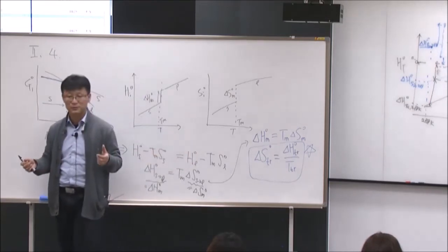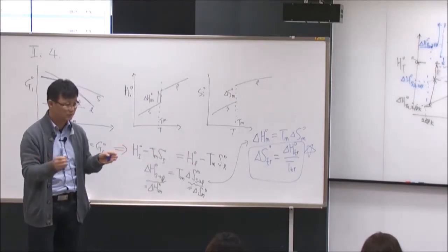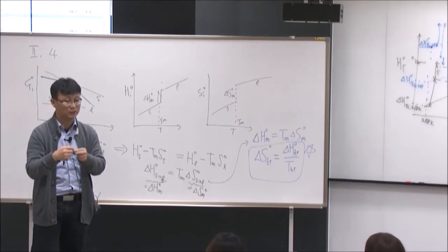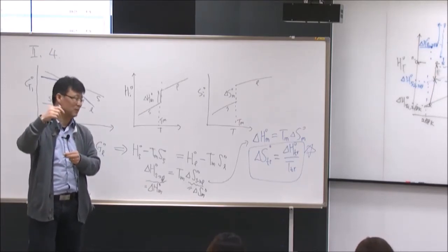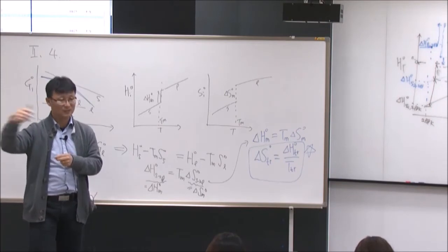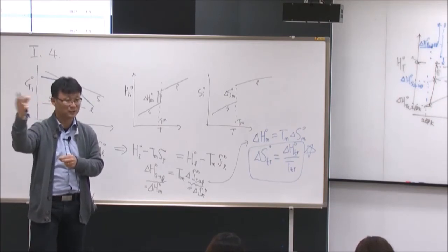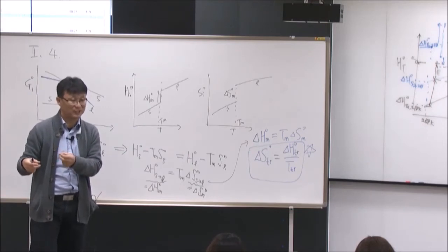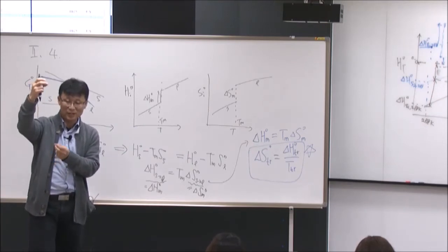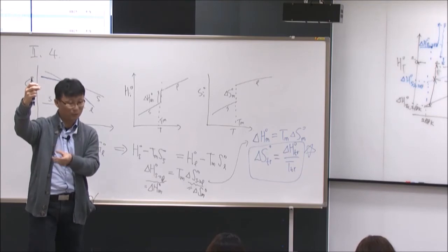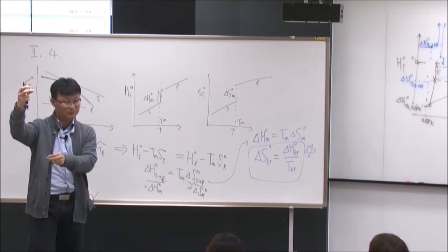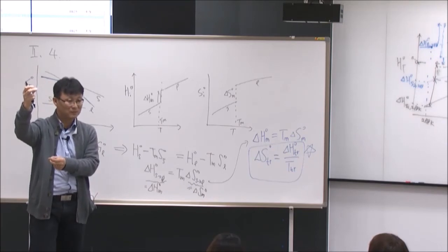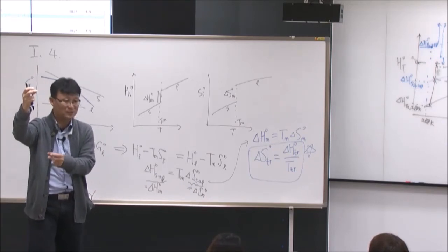So for FCC, whatever the temperature, when it transforms from FCC to liquid phase, regardless of the element, the liquid should have a similar structure, and the solid, regardless of element, has the same FCC crystal structure. So for that transition, the entropy change of the FCC material, whatever it is, to whatever liquid phase, should be similar, not the same, but similar.